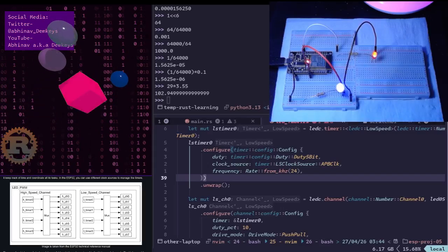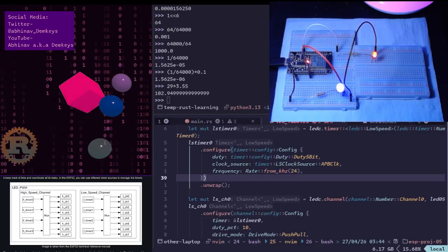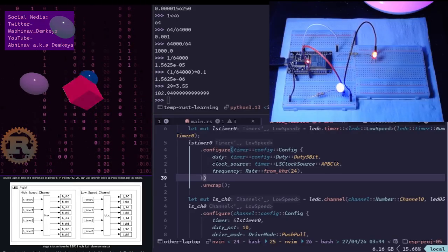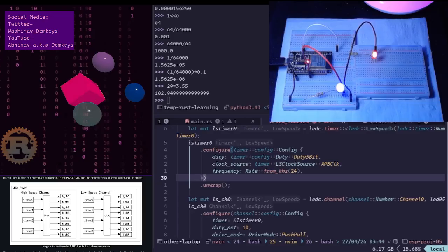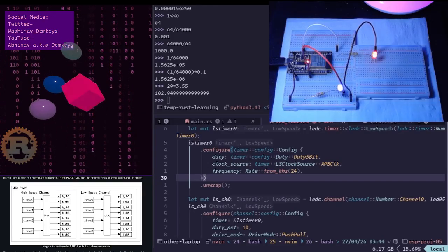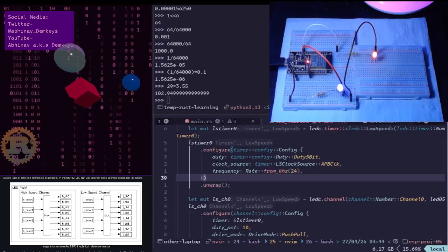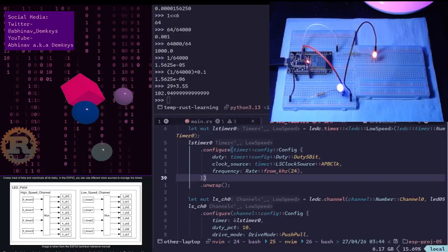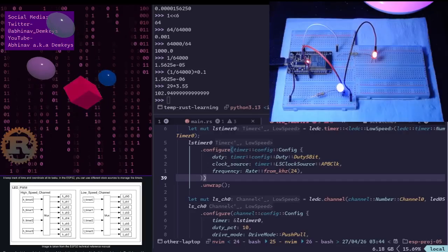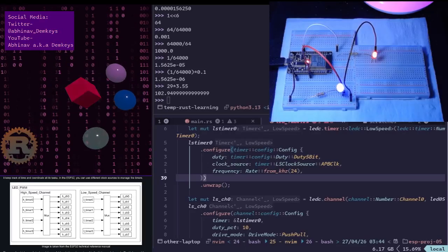When you put your chip into light sleep, the power to the CPU is cut or throttled, but the power to the post-it notes, or registers, for the PWM hardware remains on. Since the hardware is made of logic gates that are hardwired to follow the values in those registers, the PWM signal keeps pulsing. The role of the bus.